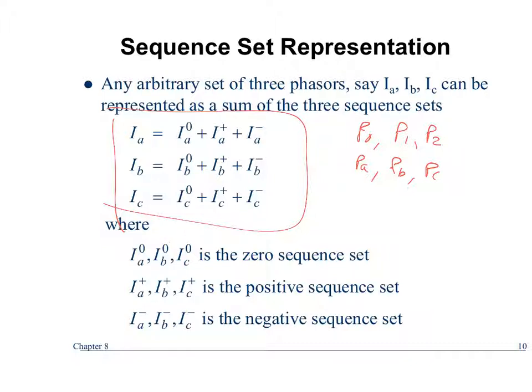You actually can do Z012, but most people don't do that because, again, are you monitoring actual impedances? No, you're looking at currents and voltages. You might calculate what the impedance is going to be based on positive, negative, or zero sequence elements, but you don't calculate specifically what Z0 is. You would just basically say that's the ground impedance.